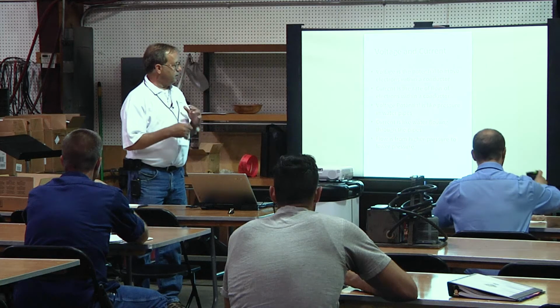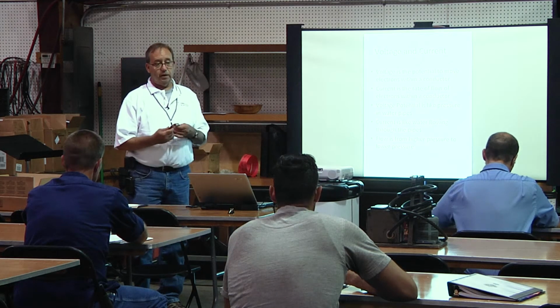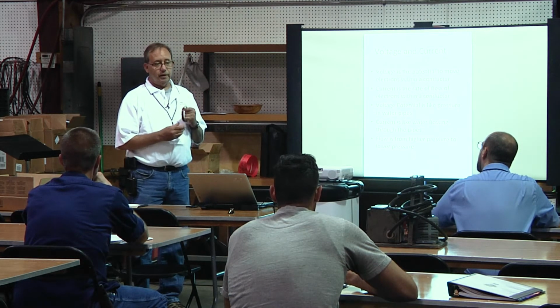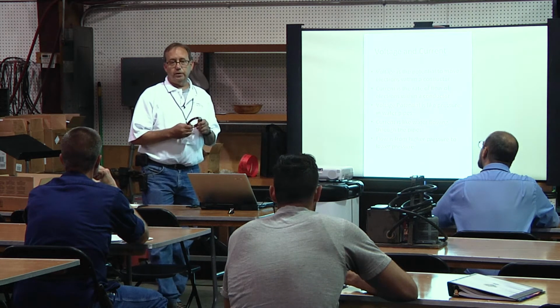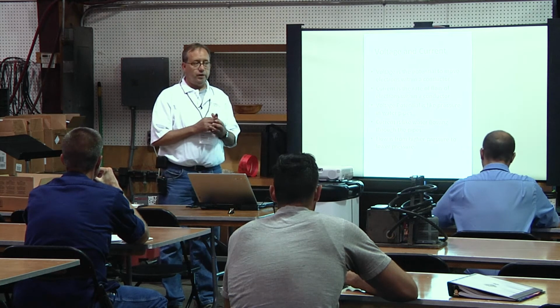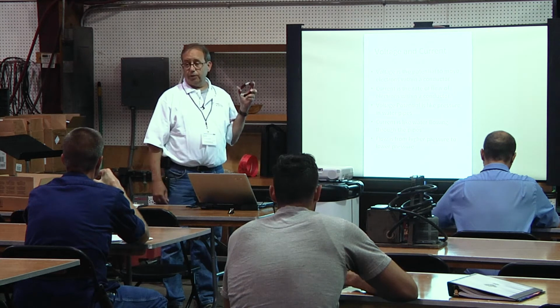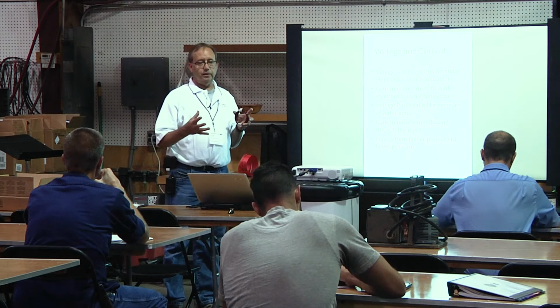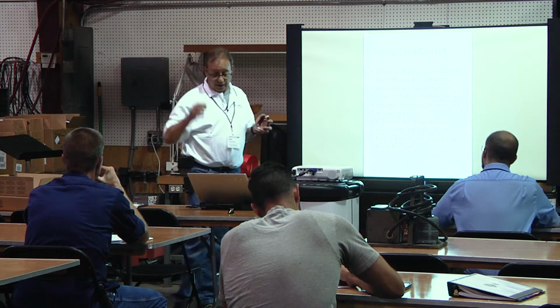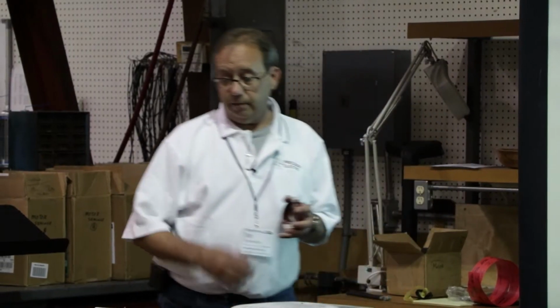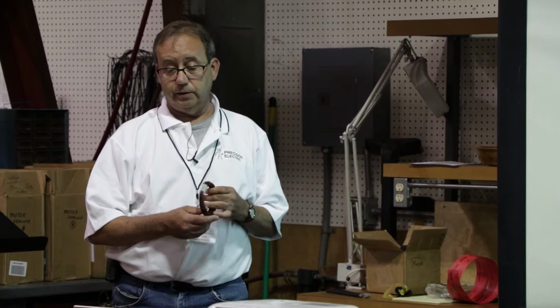So I just need to make sure everybody understands that before I move on, because it's a critical part of motor theory, as is electromagnetic induction, which is the concept of passing a field, a fixed field, through a multitude or a single conductor to create voltage induced into it without contact. I've got a little demonstration, and we can even gather around it. In order to get electromagnetic induction, you need a magnetic field, a conductor, and motion.